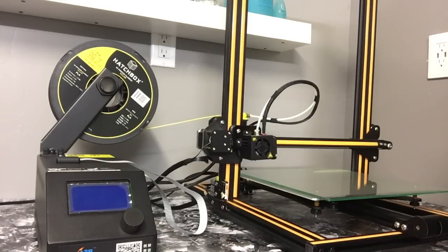Another question I get is, how much filament or infill do I use? The most common in the industry right now, most people use anywhere from 15 to 20. Anything less than that, you might have some problems depending on what kind of print you're making. Infill basically is the support of your print. So if you don't have the right amount of infill and you squeeze it too hard, or let's say you only did one layer height compared to, let's say, 3, so your outer shell isn't that strong and you have no infill, you'll be able to crush it, or if somebody sits on it, things like that.